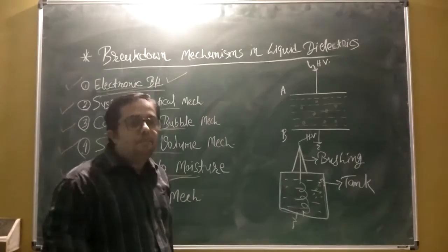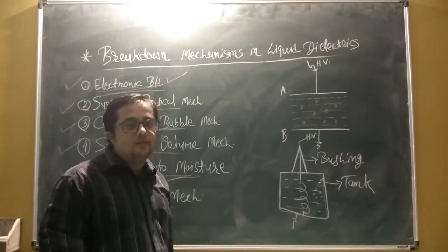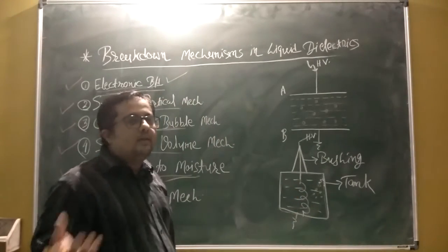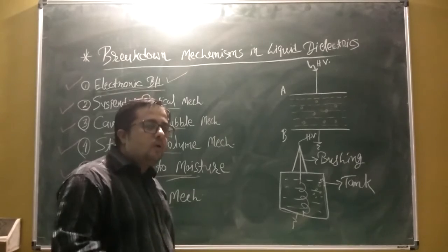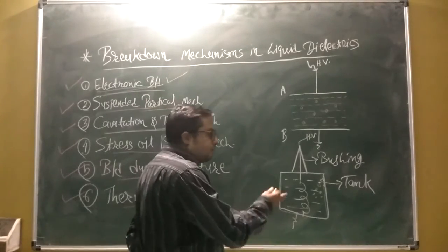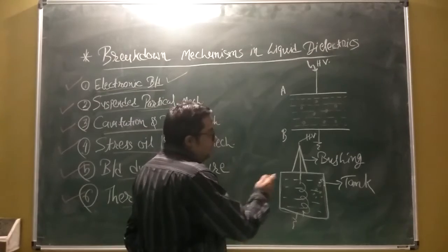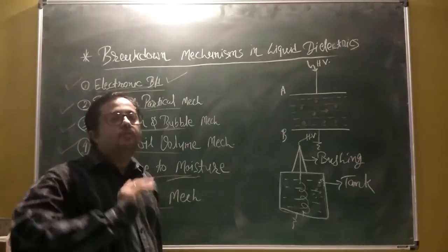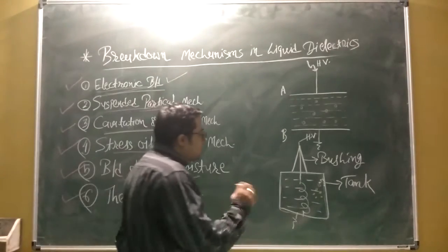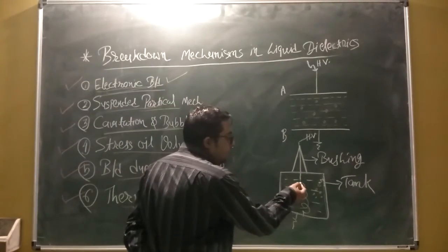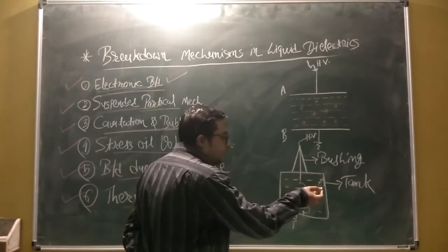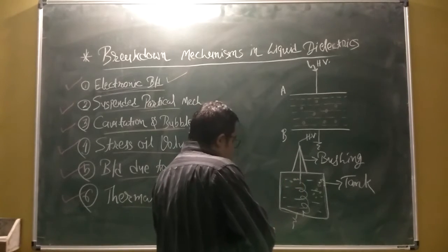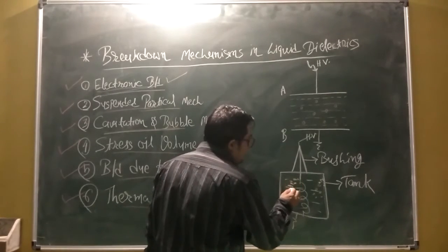So generally we are using pressboard as a solid dielectric, which is fibrous in nature. Because of these chemical and electrochemical reactions over the long operation of the transformer under heavy stresses, they may detach the fibers from the surface of the solid dielectrics. Okay, so as a result, those fibrous impurities from the solid dielectric surface get detached and further dispersed into the transformer oil.